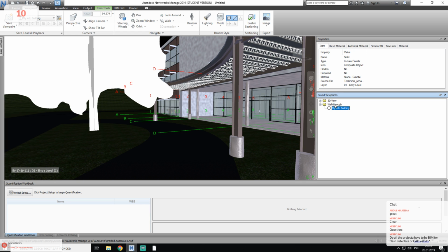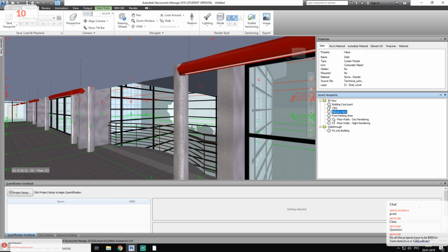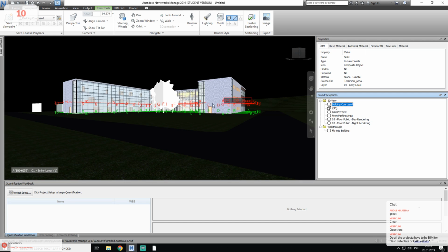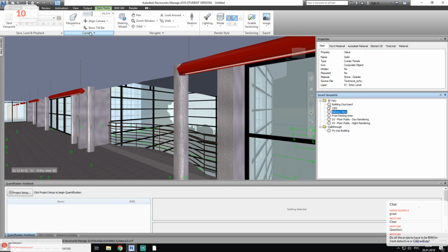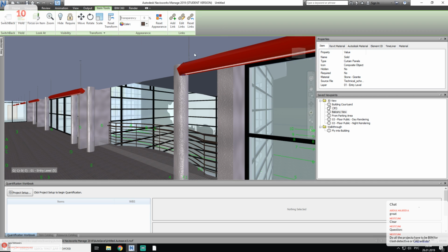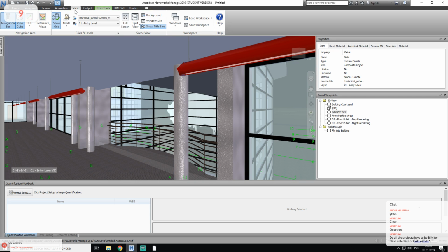For example, we have here the view from our file, because I don't actually use it. But here you can show it to your client if you want. To make this view, you can use, for example, something like save viewport, and save it like this. Okay, I'm not speaking now about BIM 360, because that thing is much more complicated than you think, because in the cloud system, in the Autodesk cloud, we have so many things which we should prepare before we use it. Okay, so let's go back to 3D.